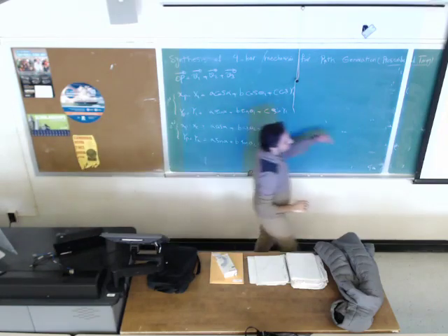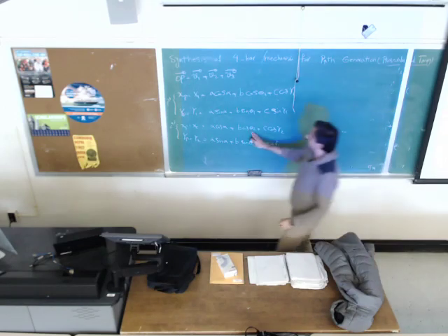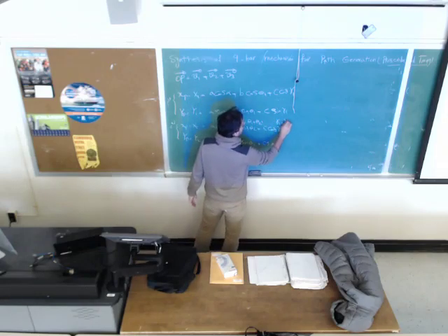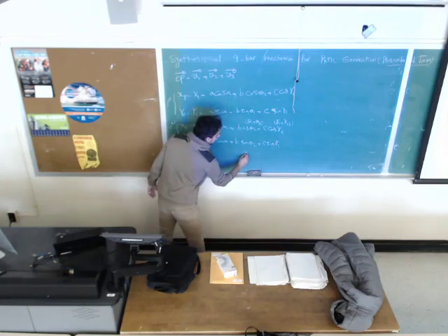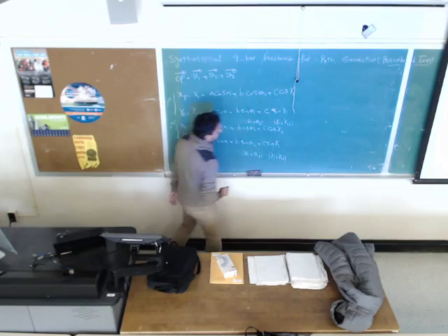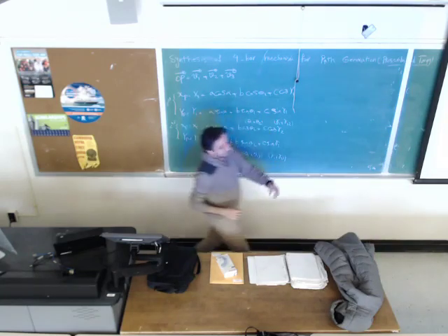You can do it for the third precision point as well, right? Have these two equations for first precision point, second, and the third. Totally, you are going to get 6 equations. Now we are writing all angles with respect to first precision point. So if I have theta 2, I replace it with theta 1 plus theta 1,2. If I have gamma 2, I'm going to replace it with gamma 1 plus gamma 1,2. If I have theta 3, I'm going to replace it with theta 1 plus theta 1,3, and gamma 1 plus gamma 1,3.